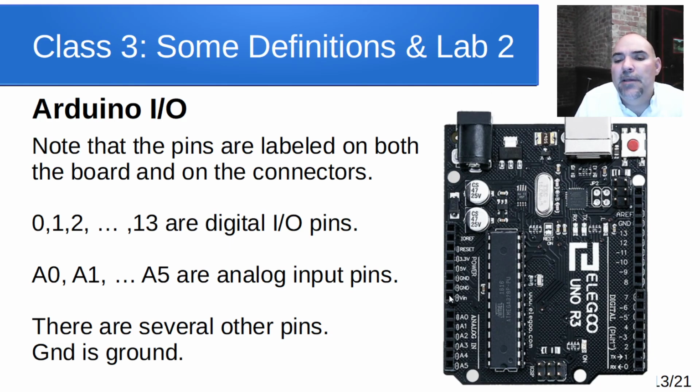There's also a VIN pin if you want to power this through that pin rather than here or the USB. You could power it from another board if you wanted to. All right, but what we care about is just one of these digital I/O pins, and what we also care about is having the ground connected. So you're going to connect ground to ground.